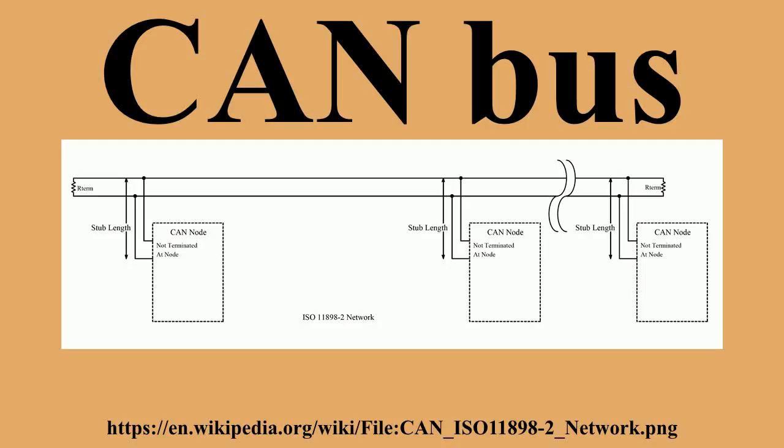By using this process, any node that transmits a logical 1 when another node transmits a logical 0 drops out or loses the arbitration. A node that loses arbitration requeues its message for later transmission, and the CAN frame bitstream continues without error until only one node is left transmitting. This means that the node that transmits the first 1 loses arbitration, since the 11-bit identifier is transmitted by all nodes at the start of the CAN frame.